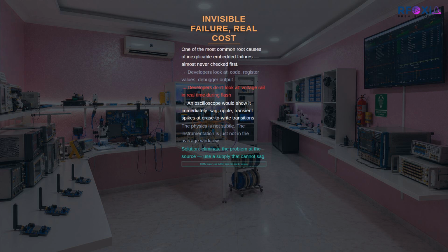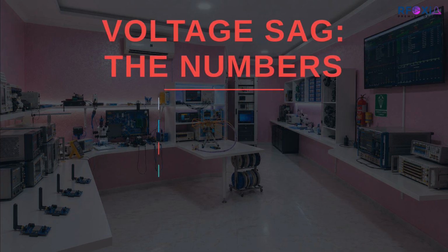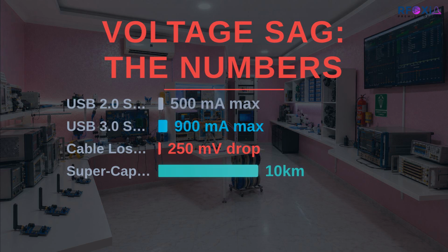A 2-meter USB cable with 0.5 ohm resistance drops 250 millivolts at 500 milliamps of draw. Before your programmer has done anything, you may already be operating with a reduced supply margin. Add the current spike from flash programming and you are now exploring the lower boundary of your microcontroller's operating voltage specification.